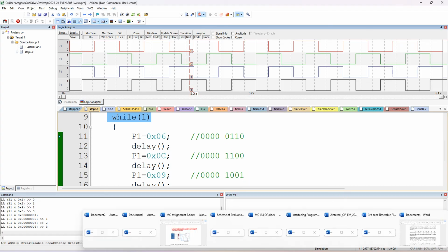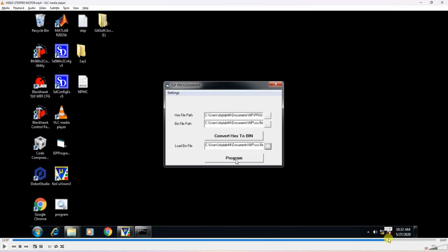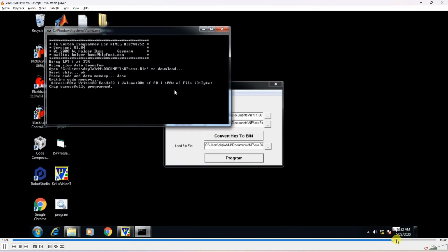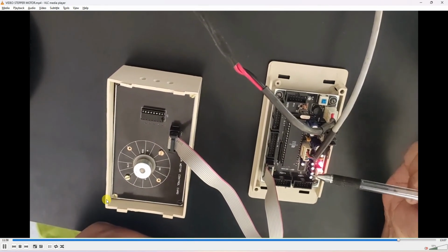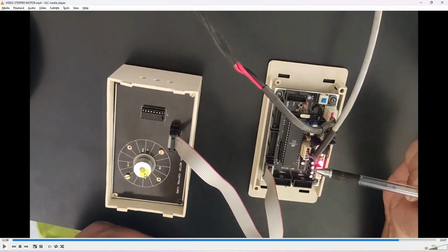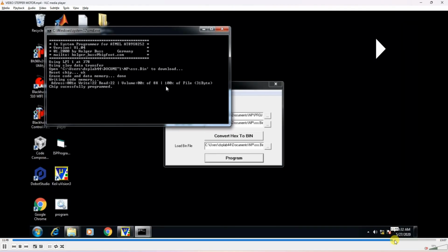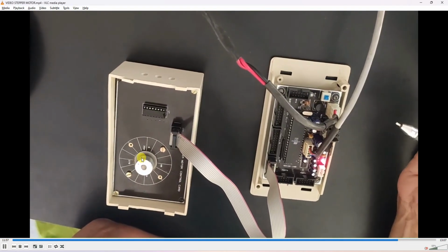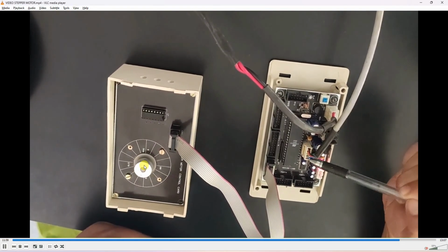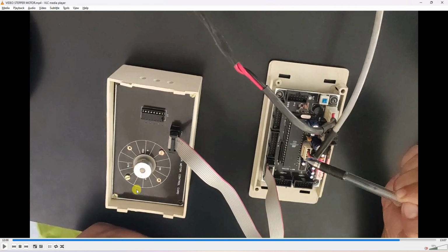And how will the stepper motor rotate? Already shown, no? So this is anti-clockwise. If you touch this, you can feel those steps. You can observe here there is a screw, which you can see when it is rotating. If you connect some screw, it will rotate. If you want to rotate the stepper motor faster, decrease the delay, and if you want to rotate the stepper motor slower, increase the delay.